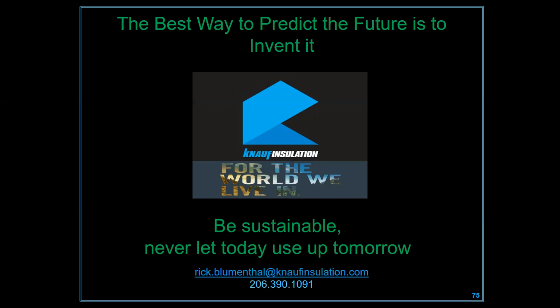Yeah, and then another one is basically talking about encapsulating attics and how nice an attic is when it's fully foam encapsulated in the summer in Texas. And he's talking about if batts have a better R value, maybe just your thoughts on an encapsulated attic with a fibrous material rather than foam. And you covered it pretty well as far as having that rigid foam in the condensation control. But in regard to a hot, humid climate like Texas, what do you think about a fibrous material encapsulated attic rather than a foam?